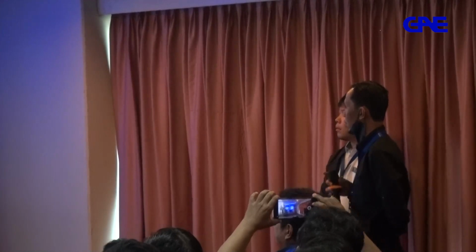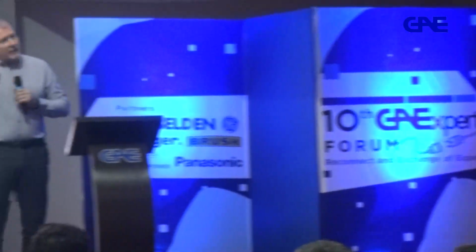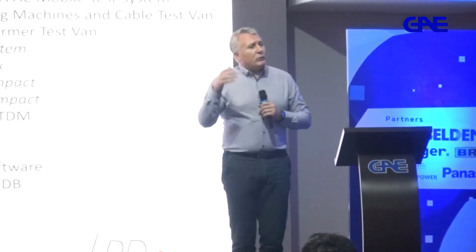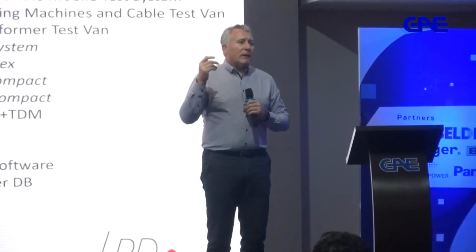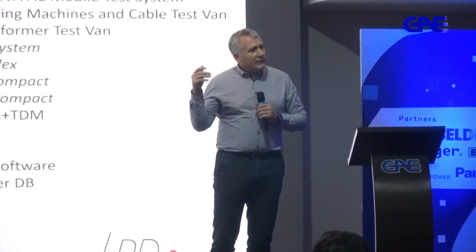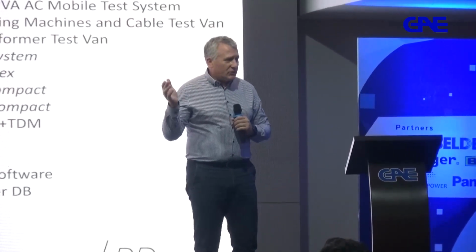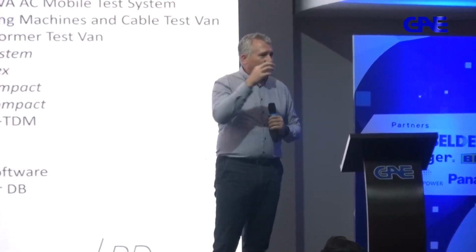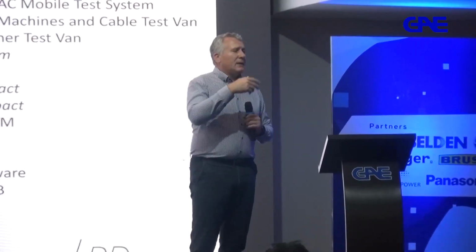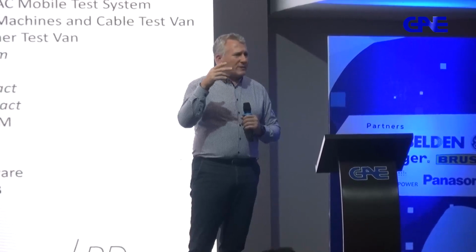So, as I mentioned to you, when you have a charge that's measured in picocoulomb, this impulse generates UHF. When you measure UHF, you measure in dB microvolt or in dBm. There is a relationship. For instance, if you have a 50 ohm impedance, dB microvolts is, I think, 107 plus dBm.